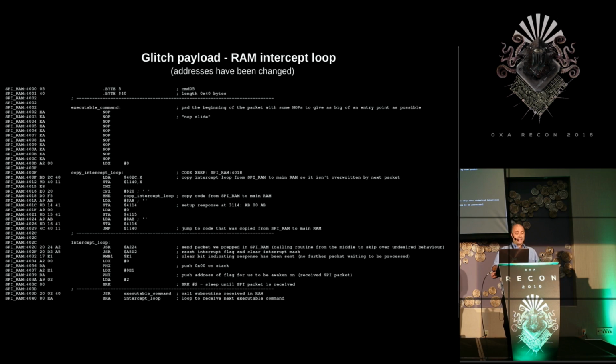So my strategy is to send code to the chip, where it goes into RAM, then glitch to cause an instruction to be misinterpreted, hoping to cause a jump into the area in RAM where my payload sits. To try to maximize the chances of success, I looked through the ROM code for multi-byte instructions, which, if broken up, contain within them a jump opcode with a destination that should lead to where my executable payload is placed. Since the ACP has a single address space, this gives really a lot of opportunities for glitching to cause execution to reach the code payload.